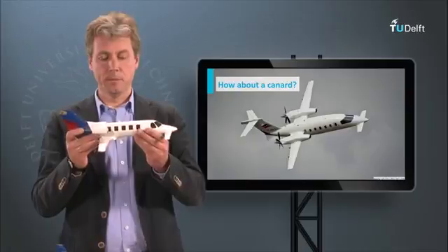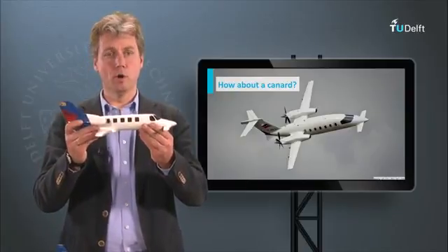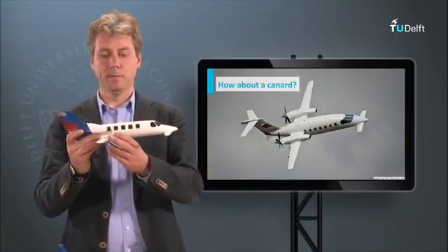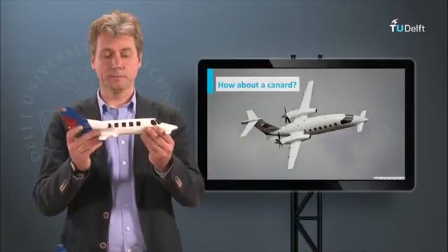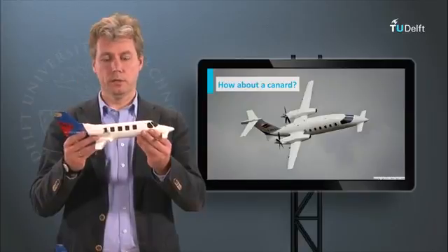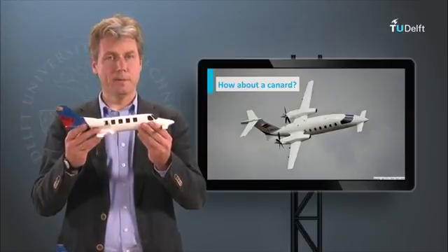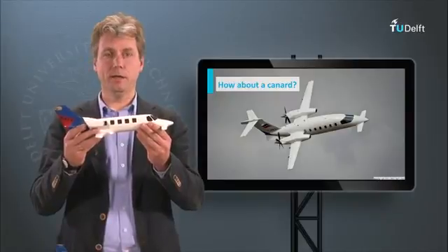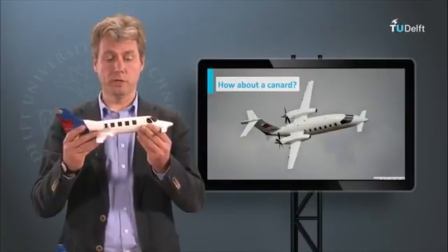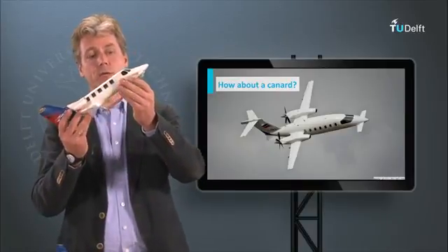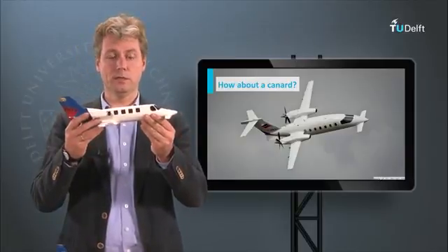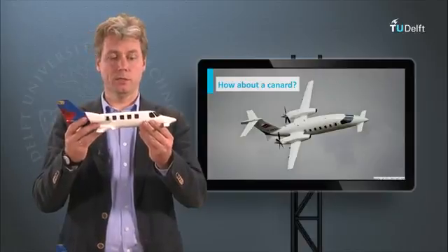But to summarize it, the idea is that you first make your moment equation for this aircraft. Now we have a lift of the Canard here and we have the lift of the wing body there, on the aft side. And then you have to first make it dimensionless, unitless, and then derive it to the angle of attack. And then you have to say the Cm alpha has to be negative, because also for Canard you want the effect that the reaction to a positive deviation alpha is a negative moment coefficient. So that stays the same, but of course some dimensions are different.